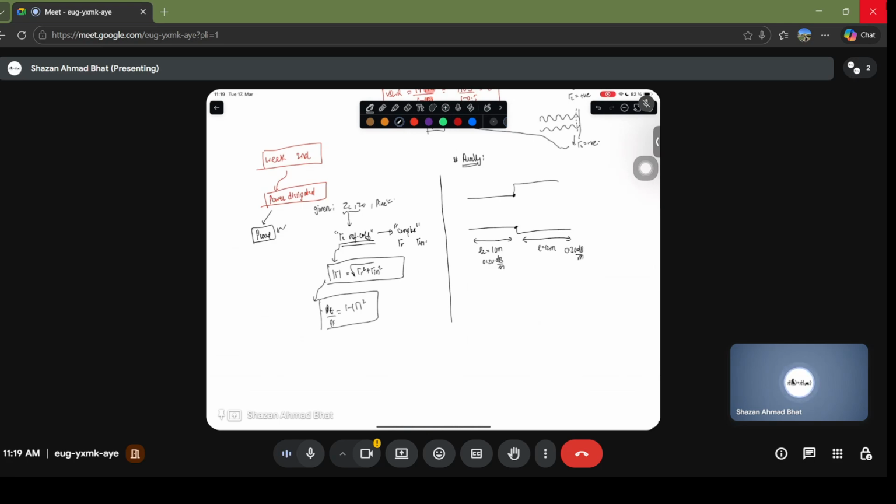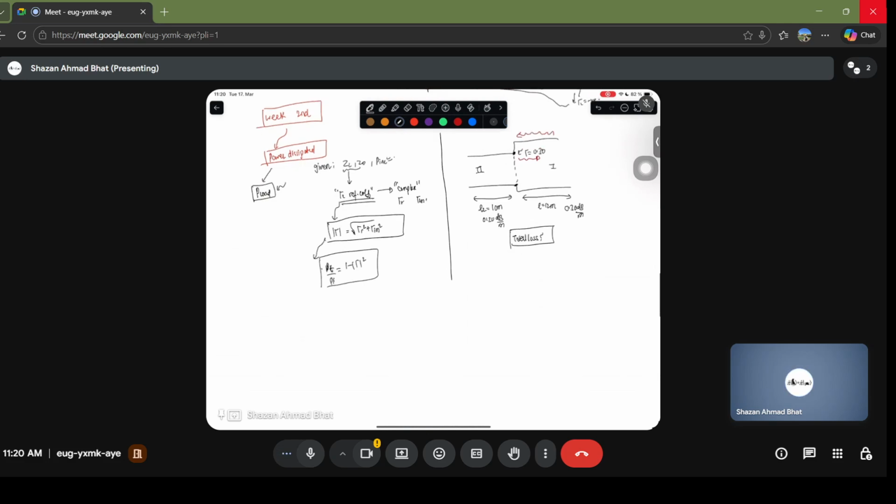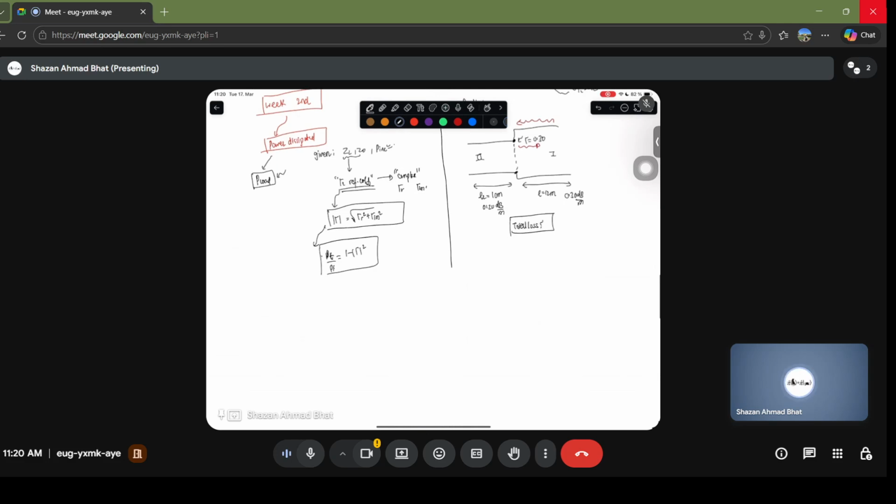And at the intersection, the reflection coefficient is essentially 0.30. So the waves which are coming here will also be reflected by the intersection. So there will be reflections at the intersection. We need to find the total loss in combination, because of the first transmission line, because of the second transmission line, and because of this interface between the two transmission lines. How are you going to find it? Essentially, you're going to find it.